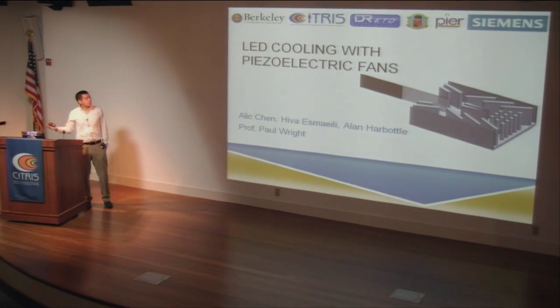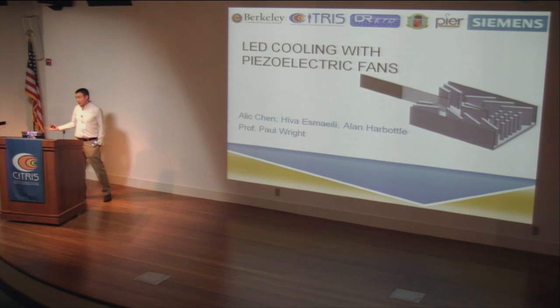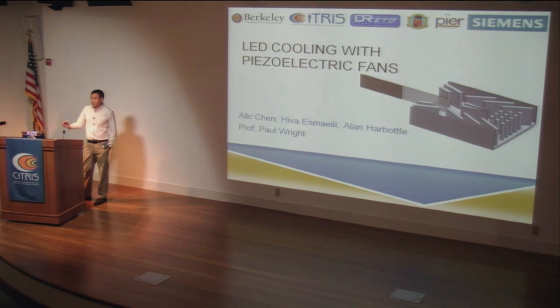So as Stephen mentioned earlier, with building efficiencies, there are multiple ways you can attack this problem. There's heating and lighting being the main thing. Looking at lighting, there's a lot of push now towards moving to LEDs because of their efficiency and longevity. However, one of the issues with LEDs is the heating problem. About 60% of the energy that's inputted into LEDs ends up wasted as heat. And as the temperature of the LED junction increases, you end up having issues with the intensity you can run these lighting solutions at, and of course the longevity of that.